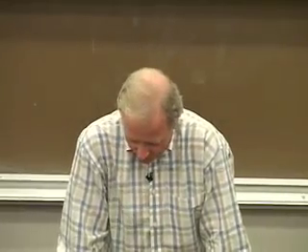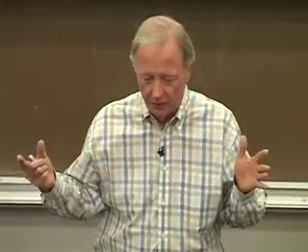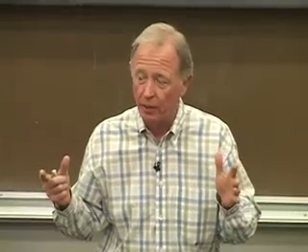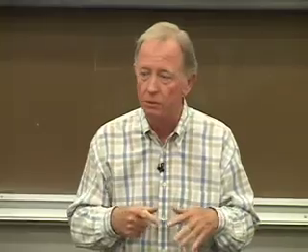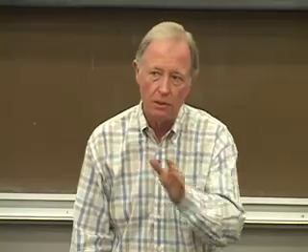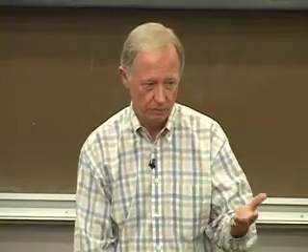And so there you have a potentially very complex problem, and you ask yourselves, what's the minimum number of dimensionless groups that I need to describe that problem? And that's what Buckingham pi gives you. So it reduces essentially the experimental challenge you have ahead of you in trying to understand how all those variables relate to one another.